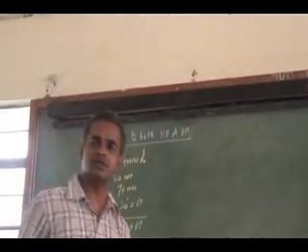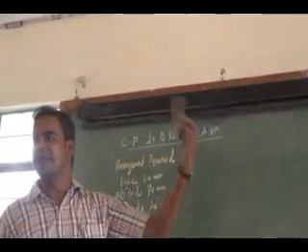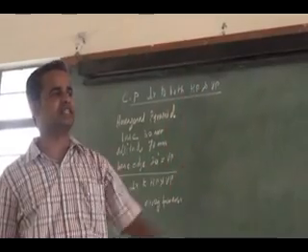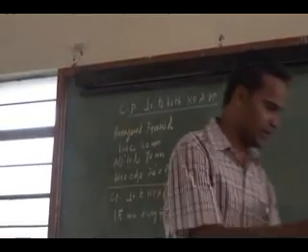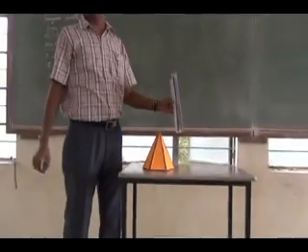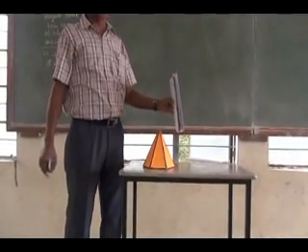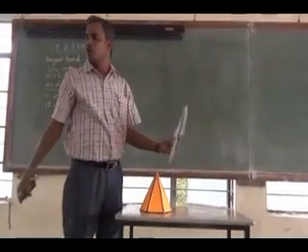Auxiliary. That is the sectional side view. Okay. The auxiliary plane will hold my side view. Right. So the sectional side view will have my true shape. Since the cutting plane is parallel to this, wherever it is parallel, on that plane I will obtain the true shape. Since it is parallel to the auxiliary plane, the side view will hold the true shape.